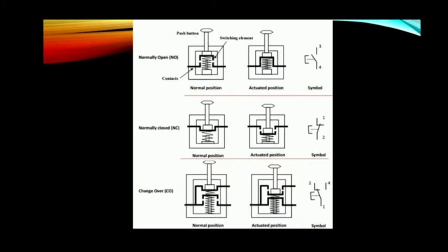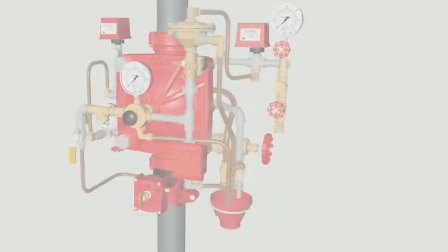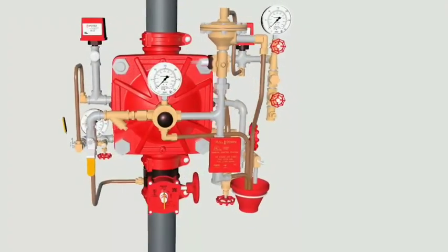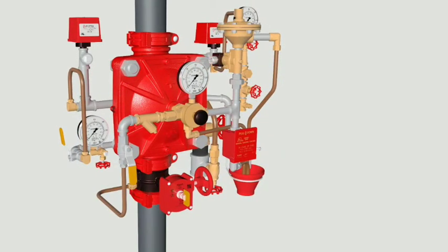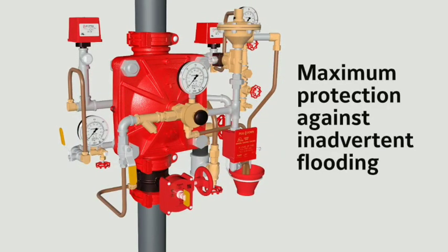a piston rod or hydraulic motor shaft, or the position of a load, is termed a limit switch. The actuation of a limit switch provides an electrical signal that causes an appropriate system response. Limit switches perform the same function as push-button switches. Push buttons are manually actuated, whereas limit switches are mechanically actuated.